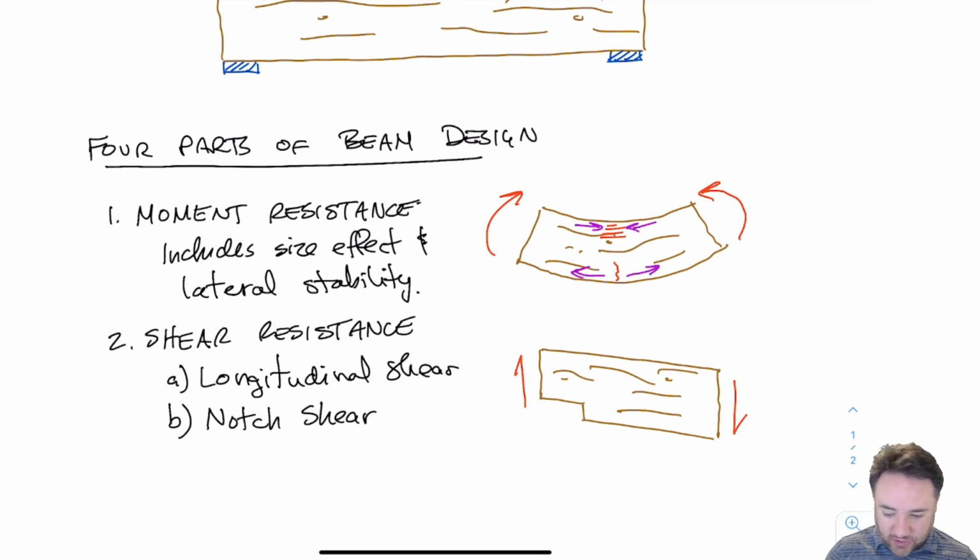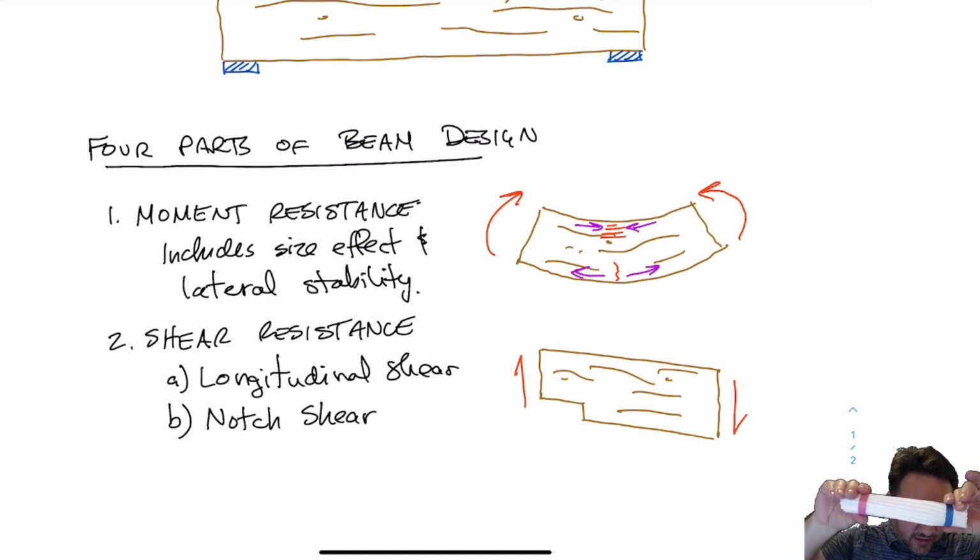So in timber, when we have shear in our timber member, and this is my bundle of straws representing the fibers in a timber section, when I want to shear that, like by going like this, the straws want to move relative to each other in the longitudinal direction. Can you see that? So these straws are sliding past each other.